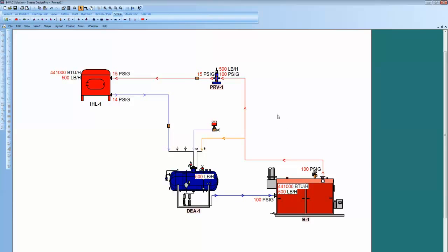Now, the system we created, the four major system parts in a steam system would be these. The boiler, which would be the generation system, so it could be a generator of some type. Then we have distribution piping, and it could be supply or condensate, pump condensate, and it might be low, medium, high pressure.